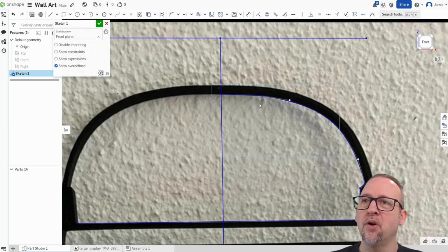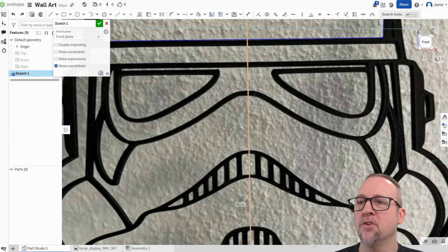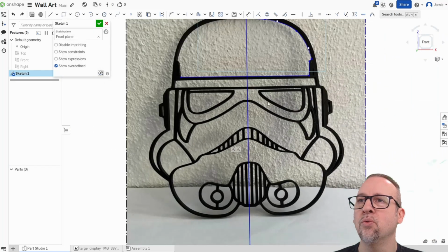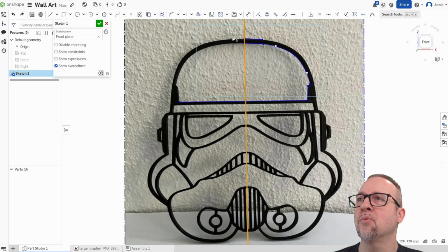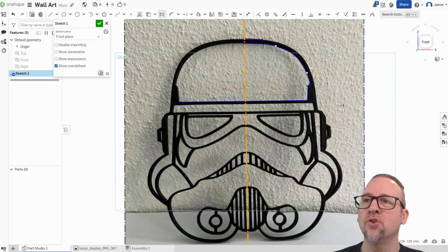Okay, so now we can start creating our other lines here. So we're going to go from here, shift key, hold that down, and then it's a little goofy there. Okay, escape that line, pull this guy down. Don't want to move that guy around, so let me fix that before I do that. I want to make sure this is good. Yeah, it's pretty much good, and this is pretty good. So I'm going to click on this guy, and then go up here and call this a construction line. So it should not move now.